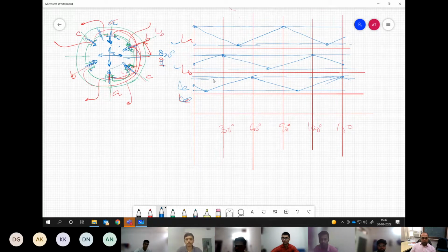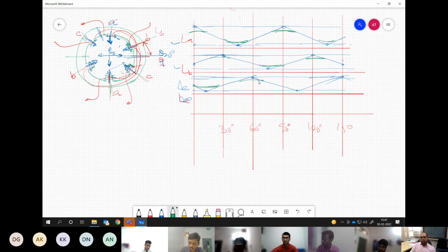Okay. So what I was trying to say is that whenever you have this kind of ideal inductance characteristic, basically this will not be so practically. It will be flat near the max and min positions. So here also you can consider like this and this. Everywhere it will be the scenario for all three inductances. So basically we cannot have much torque developed during these zones, the L_max and L_min zones, because it's almost a flat kind of characteristic over there. Where we can have it is this zone, which is kind of linear.